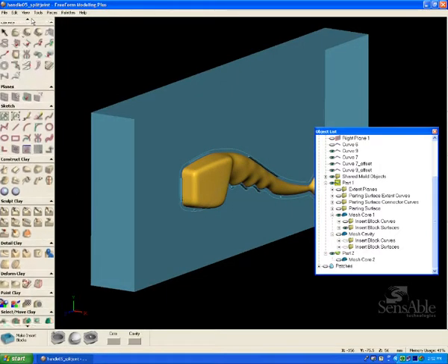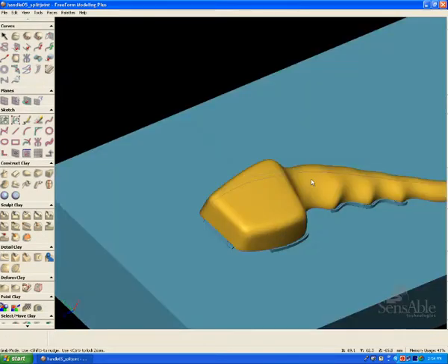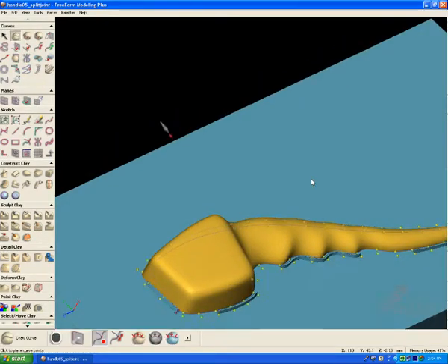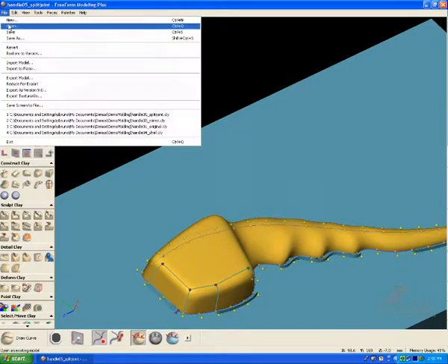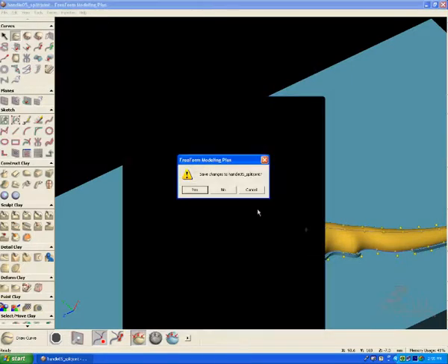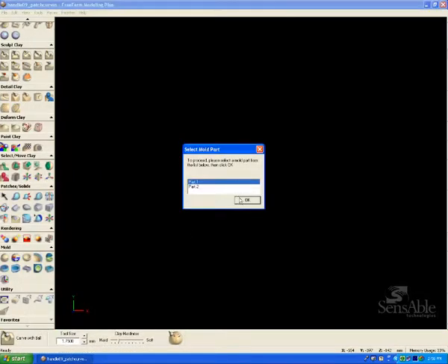Now what I'm doing here is creating two mold cavities for one side of the part. Now if this was a solid part, it would only be two sides for the entire part, but since this is a mesh cavity for a hollow part, I need to do one side for half of the part, and then the other half of the part has to have also another clamshell. So it ends up having four pieces altogether, but I'm just showing you how to do one.